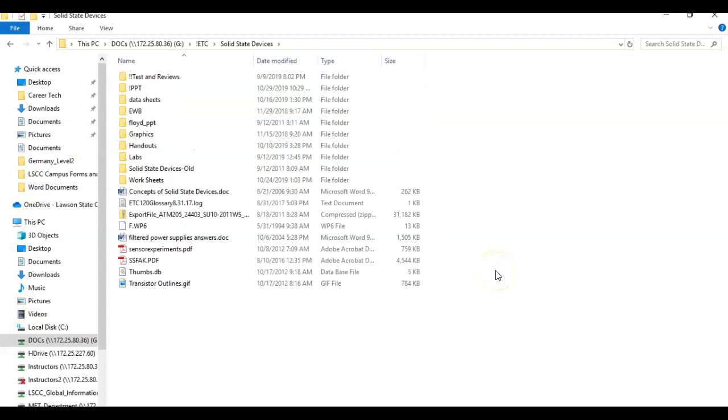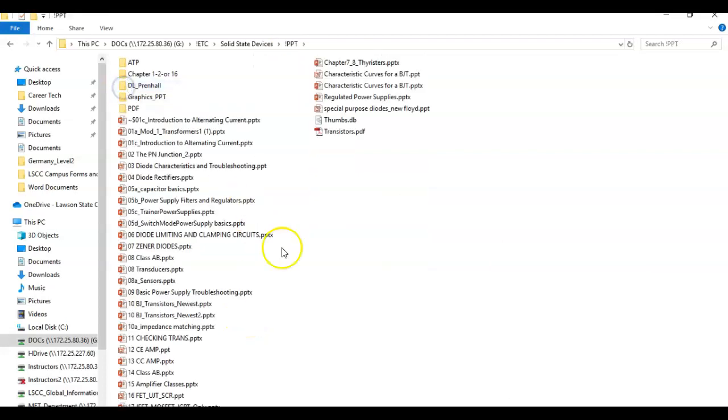When it's open, it should drop the applied voltage, whatever the voltage is, close to it. It might not be exact, but it's going to be real close. And then in the active region, it acts like a rheostat, but it's electronically controlled, right?